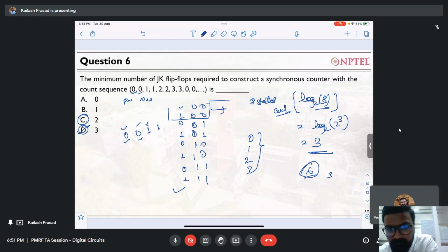I don't know. I didn't guess. The thing is, it will be different, right? Because for this, the present state and next state is 0, 0, but for this, the present state is 0, next state is 1. Right, and that is the reason why you need an additional step. Please note that that additional variable will not directly impact the output, but we require these 3 flip-flops if you want to design this.